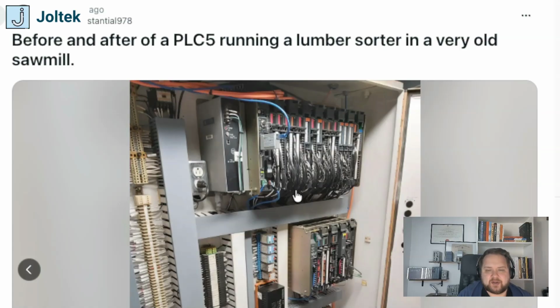Some of the cards on the 110 VAC input or output sides are going to be a little bit more troublesome because the newer systems prefer 24 volts DC, but the cards are still available, so it's possible to get them. The specialty modules, right? So if you had any high-speed counters, if you had any connections over Data Highway Plus, for example, if you had any remnants of different protocols like DeviceNet or ControlNet, it is a little bit trickier, but generally speaking, this migration is fairly straightforward for a skilled systems integrator or internal engineer from within this company.